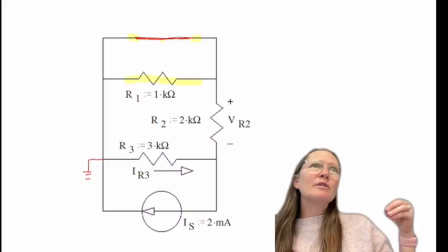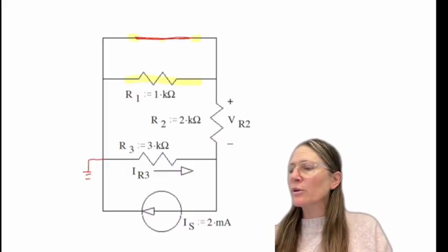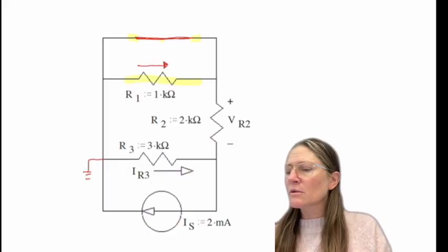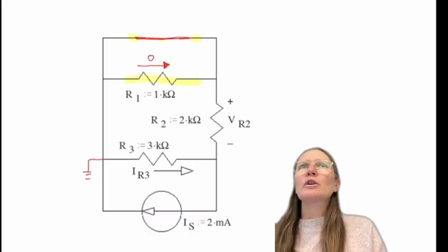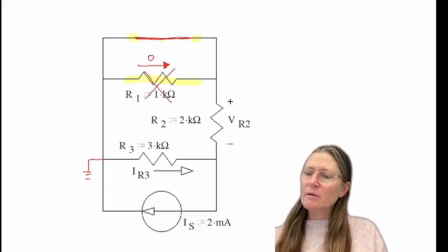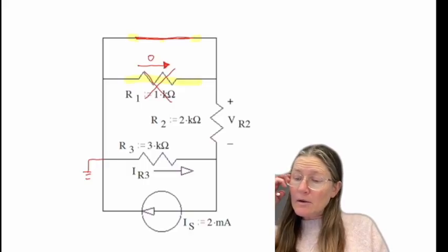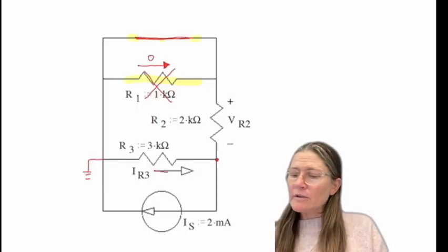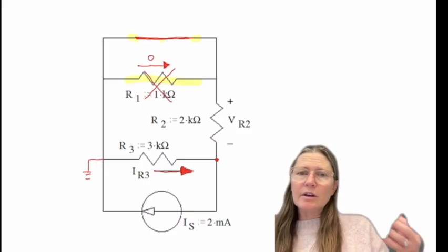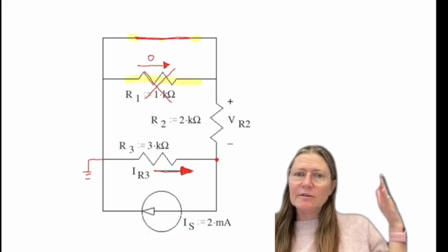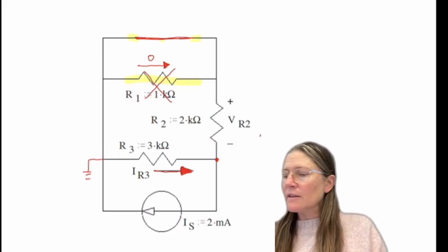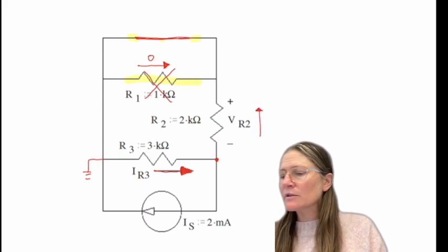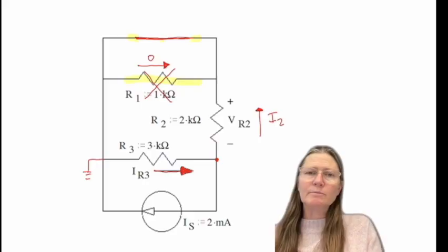So that's basically putting 0 volts across that resistor. So what's the current going through it? It would be 0 too. So I can basically ignore this one. And so I have current that I want to find in this resistor. And then now that it's not a floating wire underneath it, there's the junction of an element. This is going to be a different current. I could label it up or I could label it down. I'm going to just call it I2.